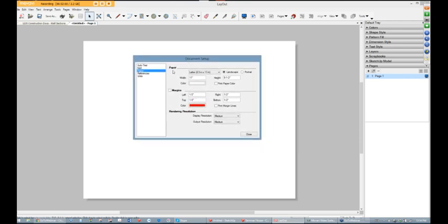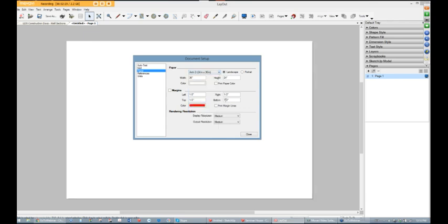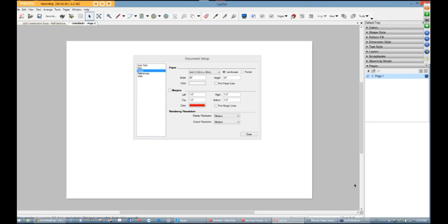And you'll notice here under Paper, there are endless sizes. This is where you set up your paper size, you set up essentially your grid, all of that. So we'll go to Architectural D, which probably most of us use, and just click on that. You'll see the shape of that paper change.